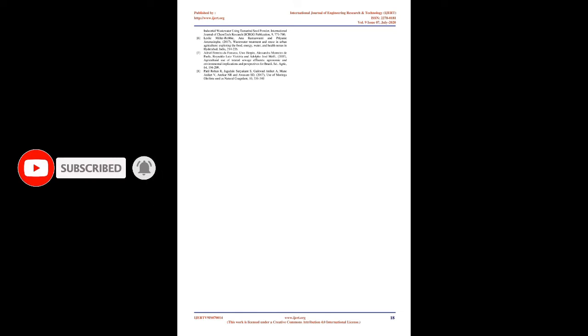In this filter, aeration is not done, but the water is allowed to settle down for 20 minutes, which removes all the waste particles. The efficiency of the filter is calculated. After that, the treated water is collected in a container, a bottle. Then the treated water is tested for pH, BOD, turbidity, and COD. Figure 2: Sewage water and treated water.